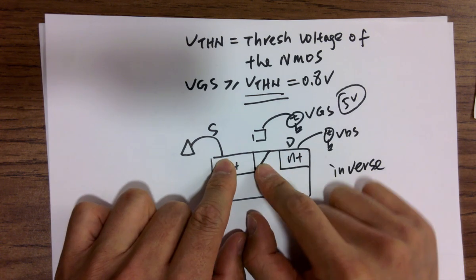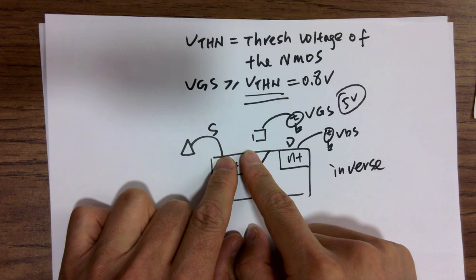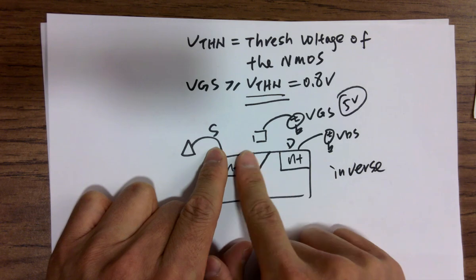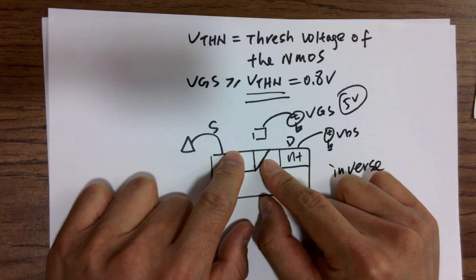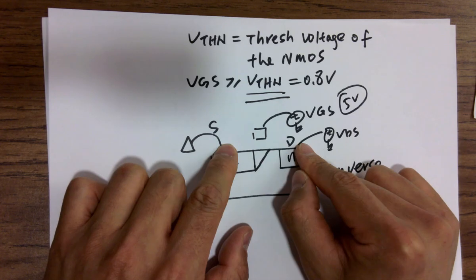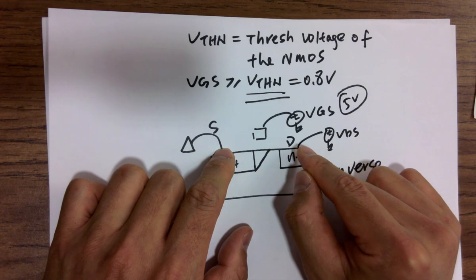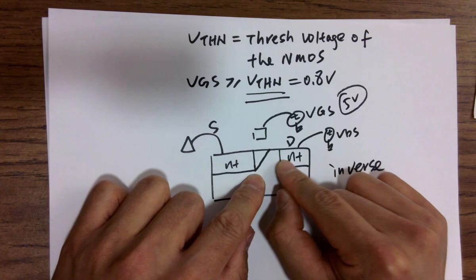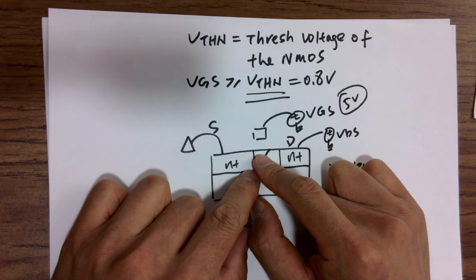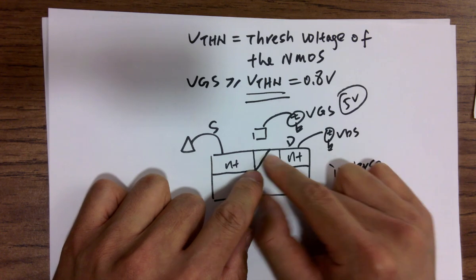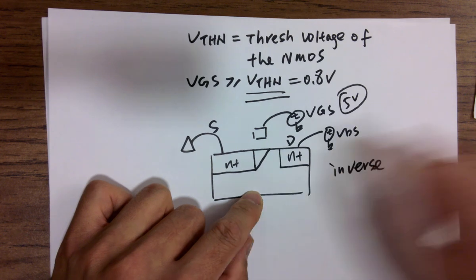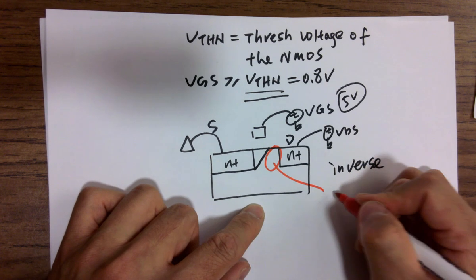Why is that? Because whenever this one keeps moving to the left, right, you do increase the pressure between the 2 terminals, but the thing is, you're also introducing more resistance. So the increase of the voltage pressure between the 2 terminals is being offset by the reduction of the available channel here. Or you can say it's being offset by the expansion of the depletion region. So this is the depletion region.